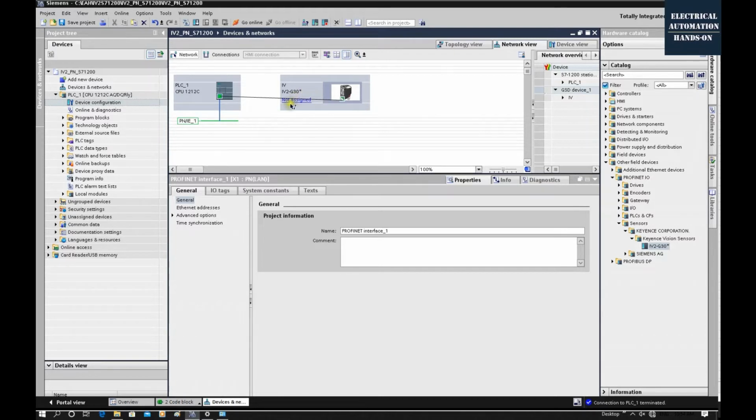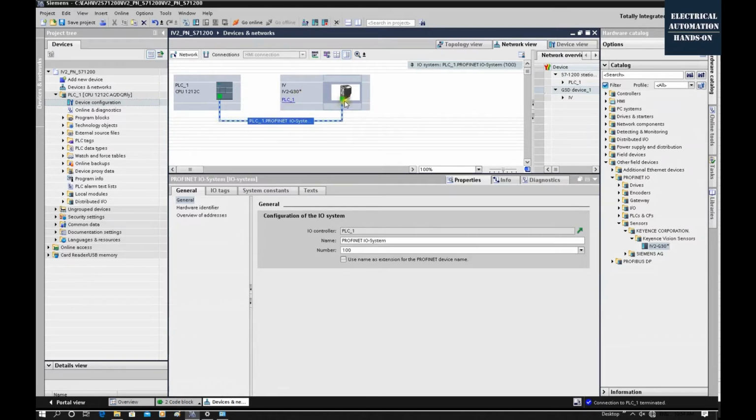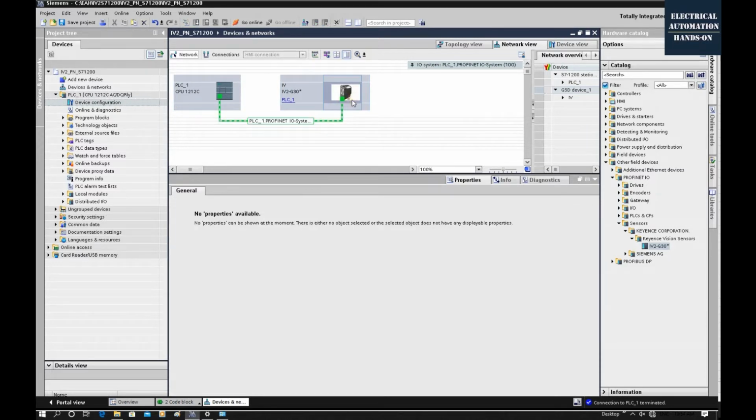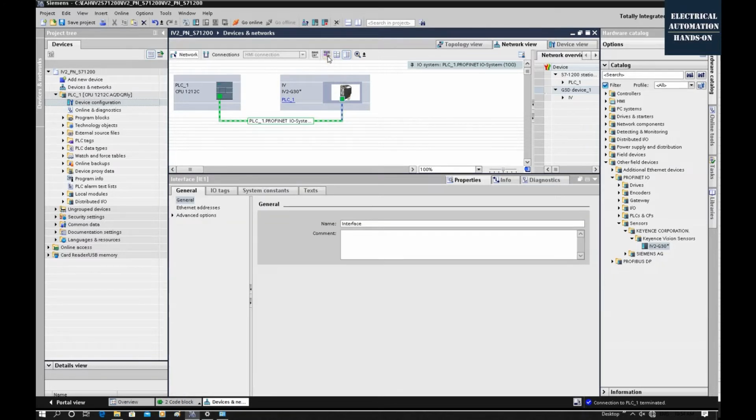Watch this name. Once you build up this network icon, that means the Profinet is already built from this controller to this device. This controller is the Profinet master, the controller, and this is a Profinet device. Another important thing is the device name and IP address. Firstly, let's click this Show address label, and we will see the IP address setting here.